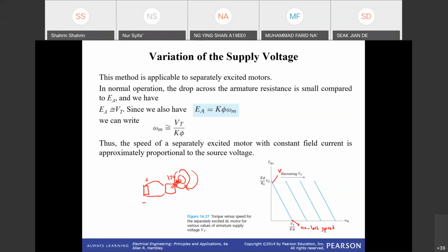Okay, so when you connect the DC motor with a tire here, we consider the tire to have a constant load, a constant torque load. Okay, it depends on the weight of the tire. The intersection between the torque load and the torque speed characteristic of the motor, where the voltage supply is V1 here, will give the value of the speed at which the motor operates.